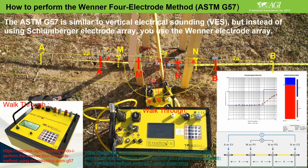You need a center point where you do your measurement. Then MN equals spacing A, and between A and M is another electrode spacing A. So the three electrode spacings are A, A, A, all similar, and the currents are outside MN. So you get the first measurement. Typically you connect the first point and this one. I can show you also what the electrode layout is. Then for the second measurement, you move the A electrode to the 2A electrode spacing distance.